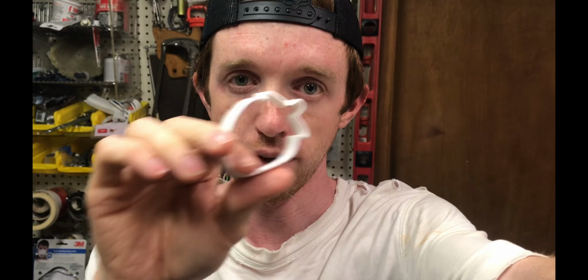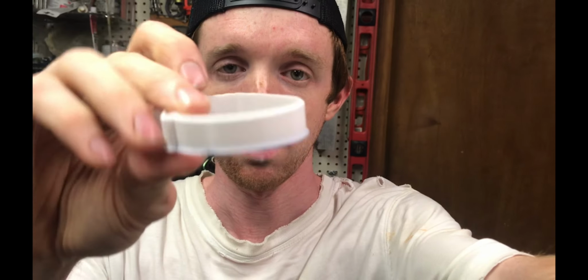But compared to the tutorial you just previously watched, I had to change how I designed it. Instead of using the simple straight line tool, I used the curved lines, I think it's called spline, and drew it that way. I found that it was much easier and took half the time. And then I extruded the height of the cookie cutter and expanded the side pieces to a good thickness so they would print. That's pretty much all I did for this one.